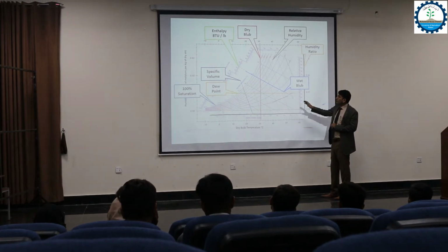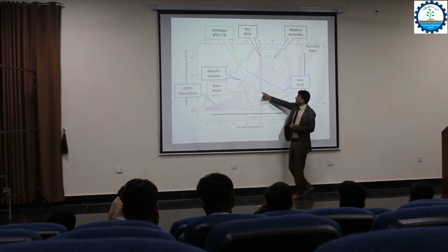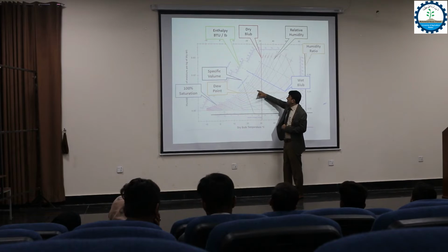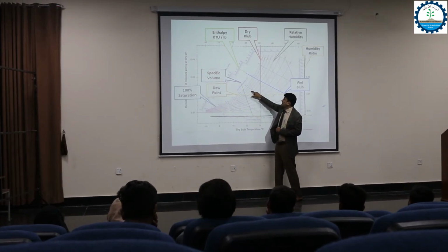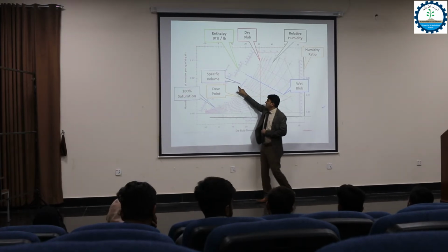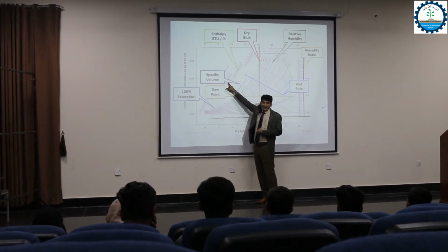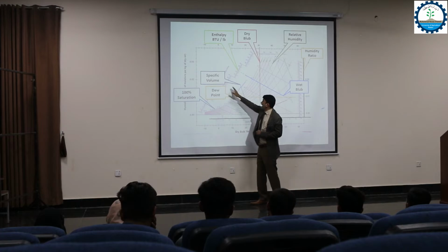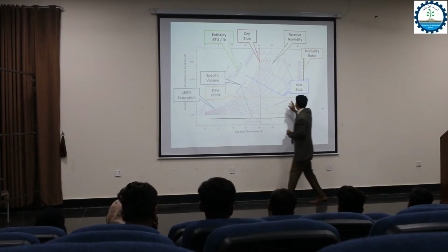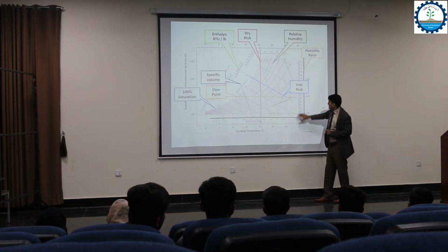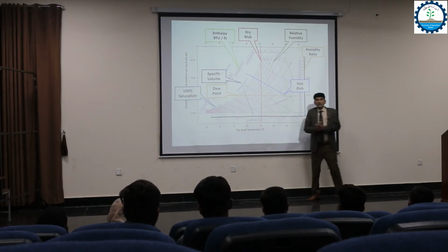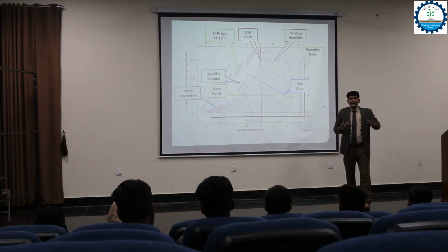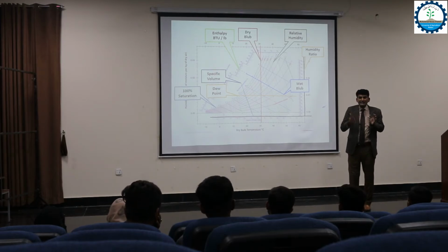So you find the point, then you follow diagonally, just like the wet bulb line, the same line, and touch the enthalpy line. There are two sides; there are enthalpy lines this way, and these are all the same. You can use your scale for initial practice.